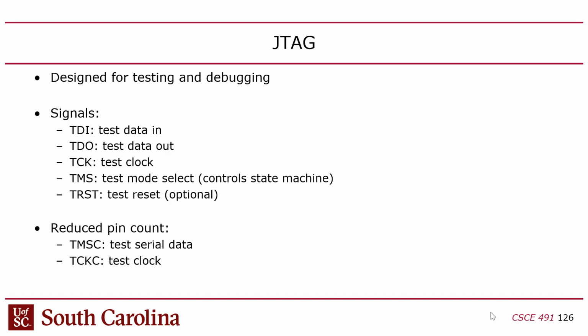Now you might say, wait a minute, that would be wildly expensive to do, right? Chips are fundamentally limited in their I/O pins, because the real estate of a chip grows as a square, the width times the height. There are ball grid arrays now, but back in the day you had pins just arranged around the edges of the chip. So the internal area of the chip would grow much faster than the I/O pin count with older chips. If you needed to read the whole internal state of the chip just for debugging, that would eat up all your I/O pins.